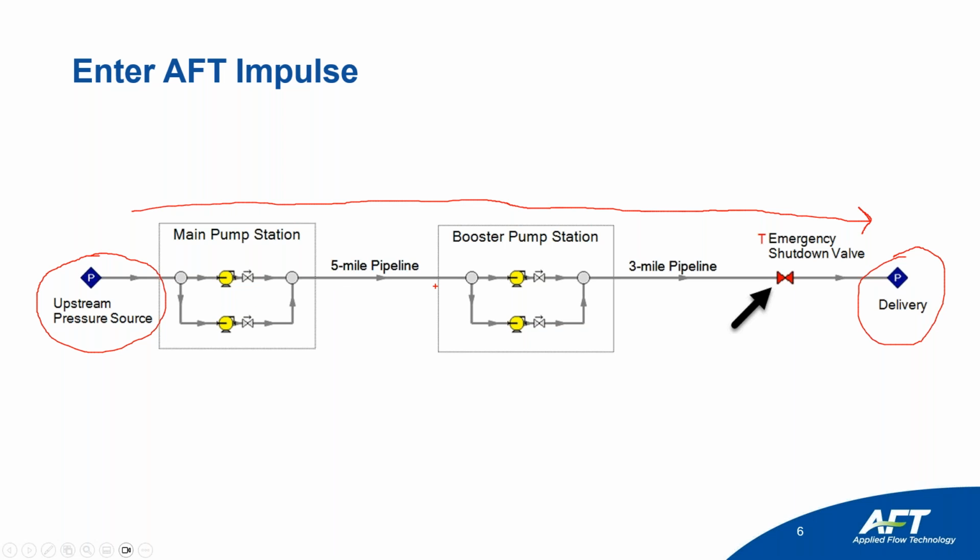So in the middle, we have a very long pipeline, and with pipelines, as the code suggests, you typically have to worry about surge. Simplified calculations, or just assuming my system will be good enough, is not good enough, because there's lots of things that can happen that are unexpected that simulation software can help predict.